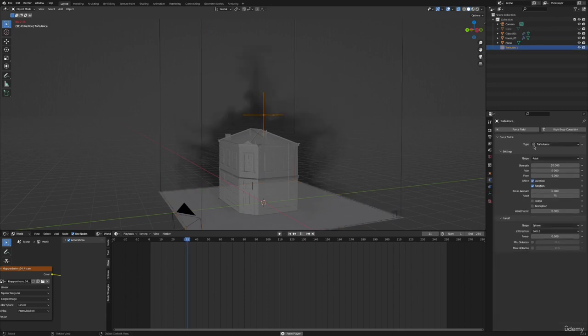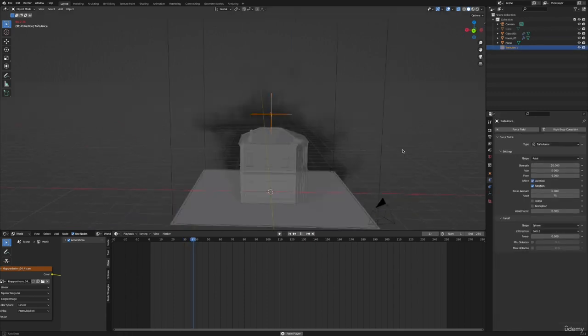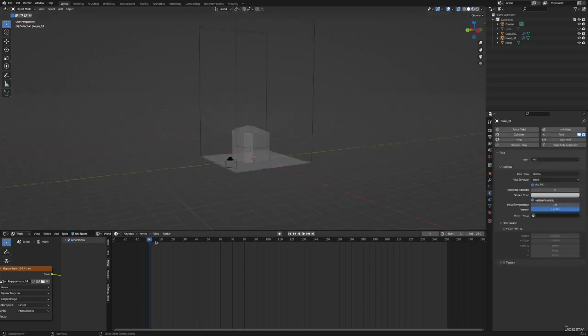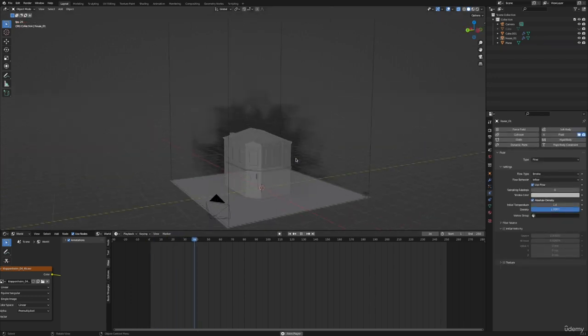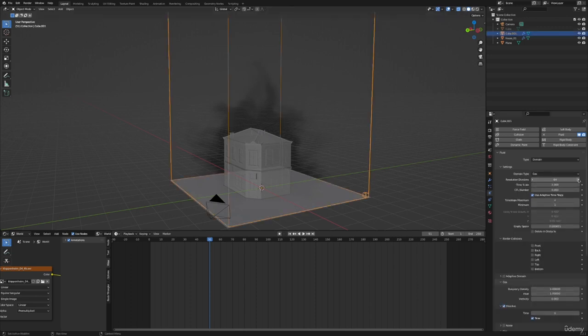Now, of course, you have a complete chaos simulation here, but we don't want to keep that as it is. Of course, we can change that again by selecting the domain, and we put it up once, we put it down once. And that said, whenever you see something and expect some change or something special and you're not getting it, just go to the domain, put it up, put it down again, and then the whole thing can be reloaded, and then you get the result that you want.